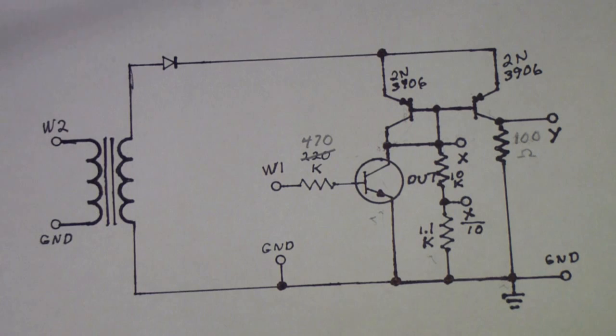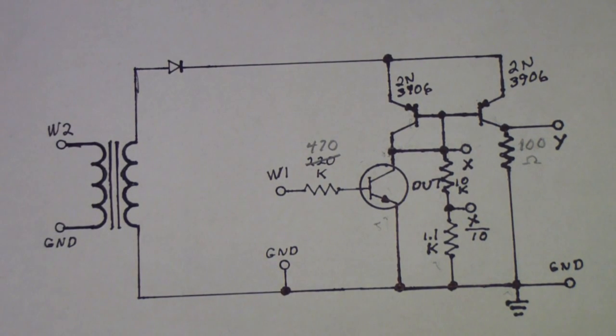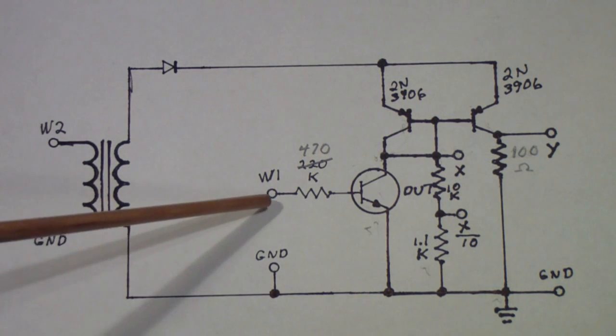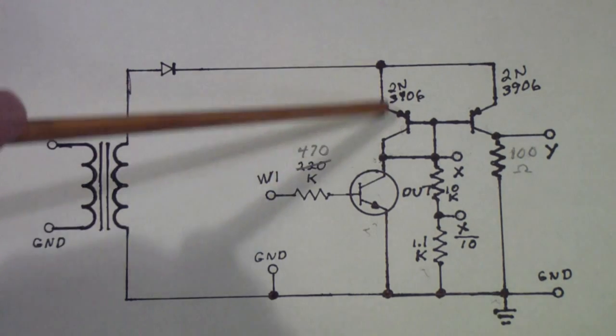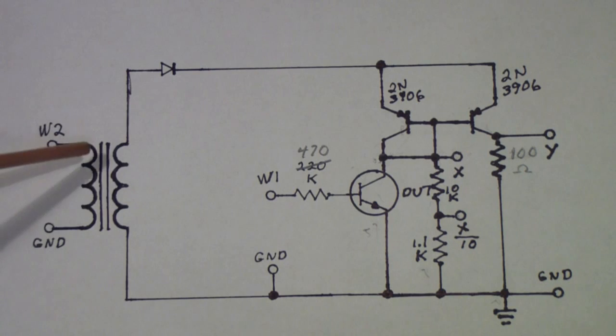So I hope this has been a useful exercise for those of you, whether you're interested in building a curve tracer or not. The point of the series of videos was more to illustrate the design process, where you identify the weaknesses in your design and then you try to provide for them. Early on, we realized that one of the weaknesses of the design was the 100 ohm resistor here. We changed that to a current mirror.